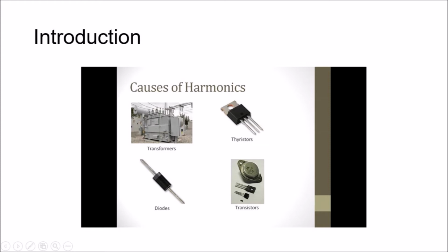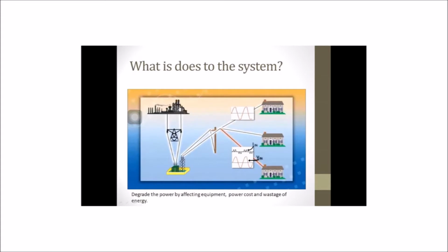The power quality events are voltage swell, voltage sag, undervoltage, overvoltage, interruption, harmonic, interharmonics, transient, and notching. Monitoring and analysis of power line waveforms are assessment of power quality events. It's essential to measure voltage, current, frequency, harmonic distortion, and waveform to monitor the power quality. The use of power quality monitoring is to locate the source of the events that occur.